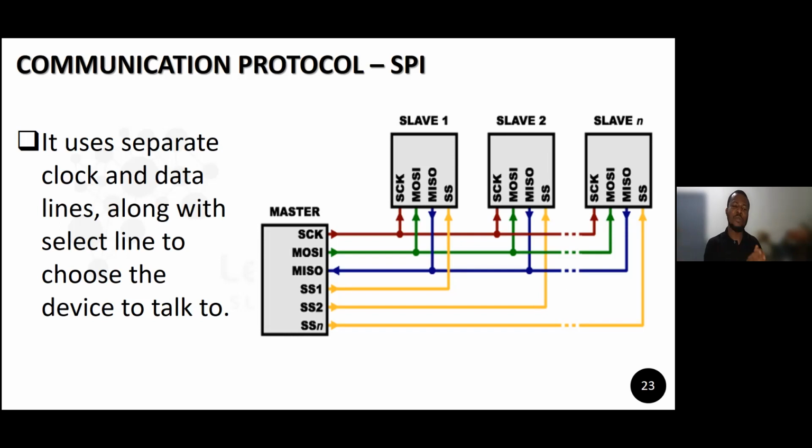But then there comes a point where you can only use SPI because some devices work so fast that you can't hook them up with I2C, you can't hook them up with UART. So they will require the speed of the SPI, okay? Most often, this is not something you choose. Usually the modules come with the communication protocols already embedded. The manufacturer of that module determines that, okay?